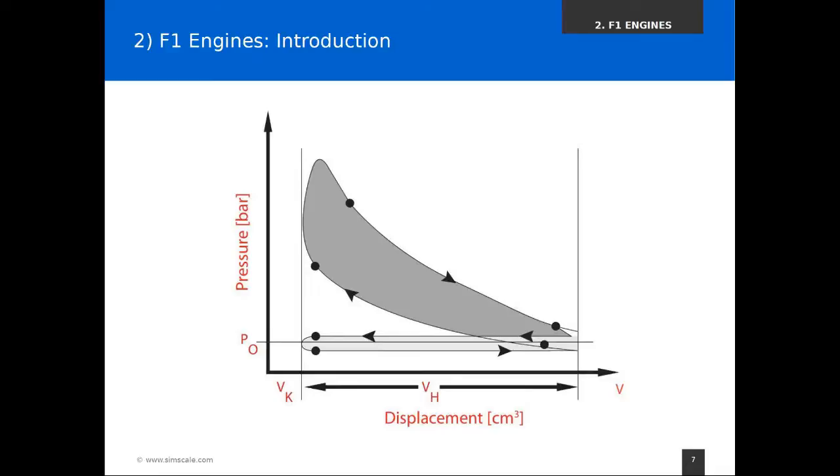We just hold it steady in a certain place. That means that we're not changing the shape of this curve, but if we are having higher revolutions in this engine, this amount of energy is just going to be released more often. And this means that the power output of the engine increases. So RPM basically is one factor in the power output of an engine.